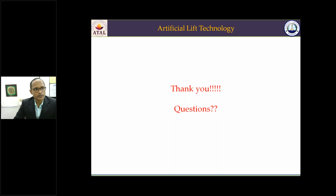So that's all about the artificial lifting of oil. We saw that the artificial lift methods are used in order to pump the liquid, or to bring the liquid, from the subsurface to the surface. Different types of artificial lift methods are there. In gas lift, we are injecting the gas. The SRP operates on the principle of a hand pump. In the ESP, we use a multi-stage centrifugal pump. There are also other types of artificial lift methods like hydraulic lifting, jet pumping, and the PCP, that is progressive cavity pumping.